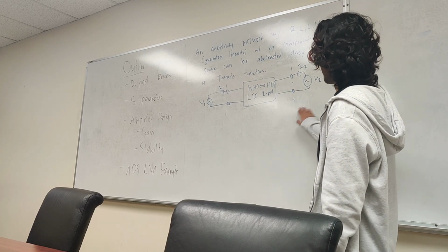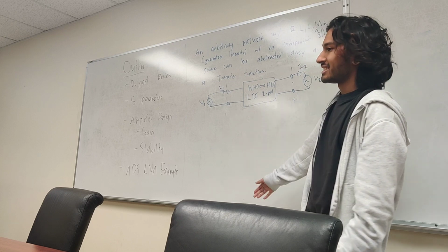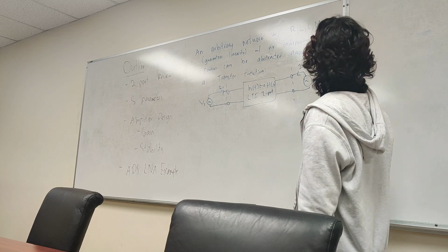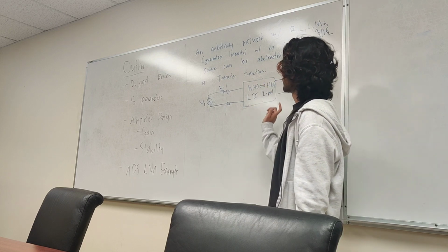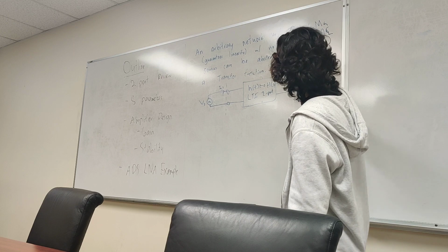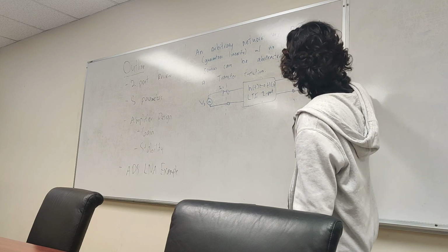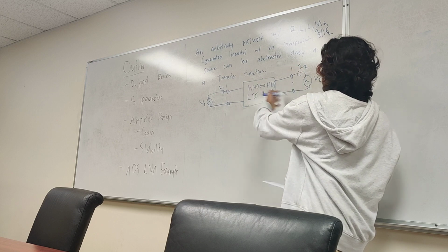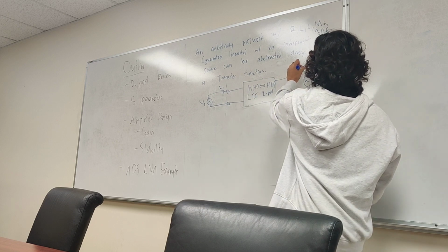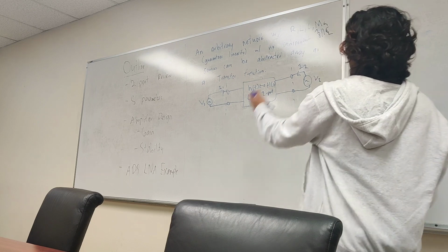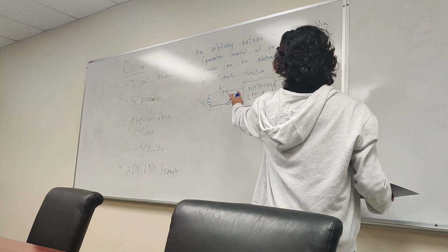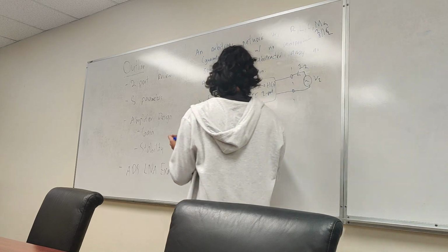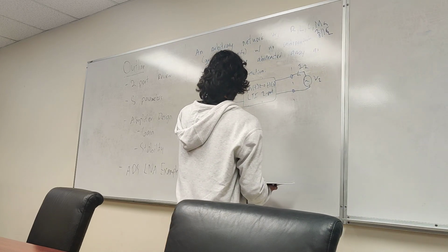If you look back at what we did in the earlier modules where you're doing an AC sim, you can't have an excitation at the same time at the input, you have to null it. So if you want to figure out the V2 with respect to whatever you're putting in over here, remove this voltage source, open it like that, and you can measure it. But generally speaking, you can attach voltage sources to both sides of it, and you can get corresponding currents as a result. So is there a way to capture this relationship, where we have a voltage on each side that has a corresponding current going into this network? Is there a mathematical formulation here? And there is. We can just make a matrix.